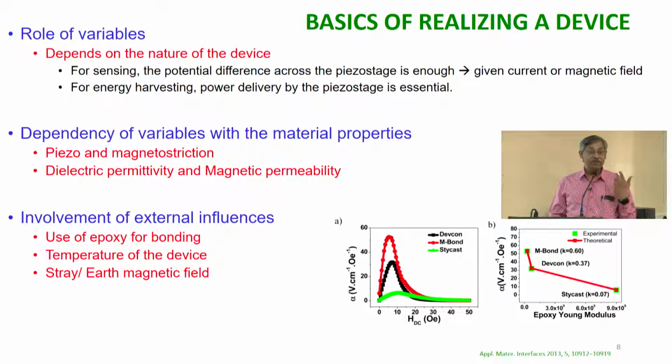If you are going to make it for a sensor, you should know what you are going to measure, and what else is around. You are not only measuring the magnetic field from a motor, but there are several other magnetic field sources around. The known source is immediately the Earth's magnetic field, but you have several other sources coming into the picture. Even other nearby vehicles or motors will affect that. So one has to be careful with that.